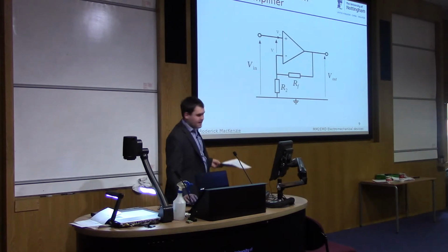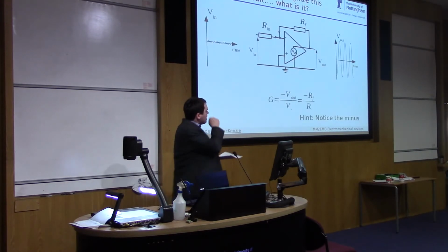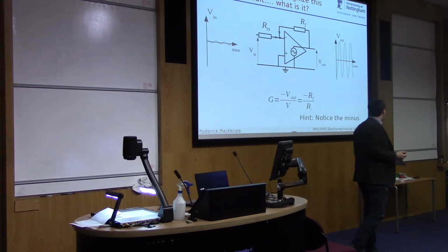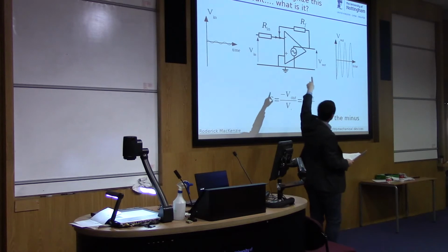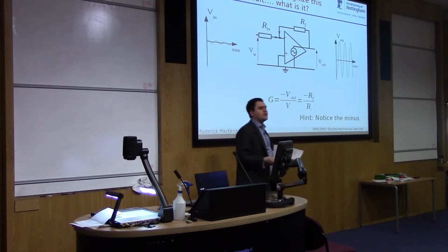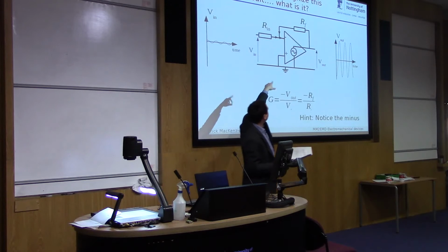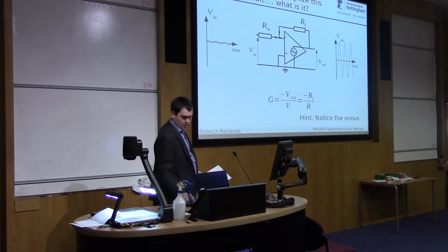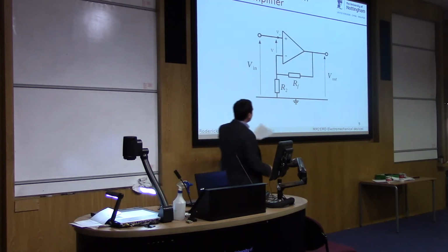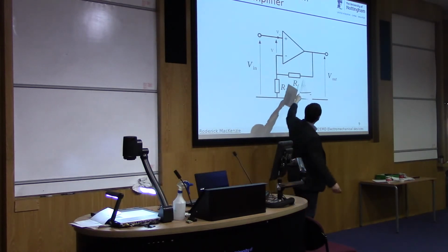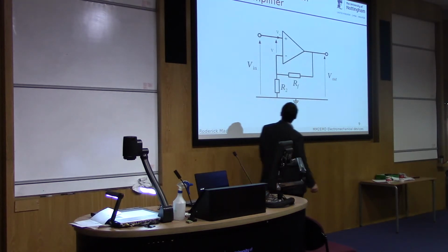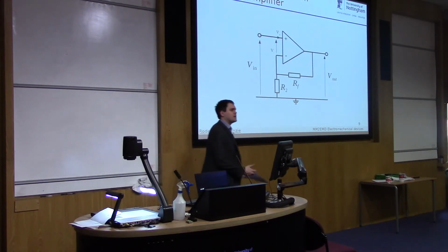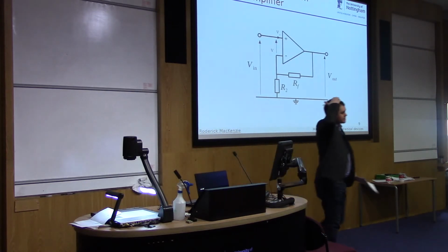And if you then look at the circuit, I know Arthur's been teaching about potential dividers. If you look at that top bit of the circuit, you can see it's a bit like a potential divider, and the centre of the potential divider is going into the negative pin. Well, you see the same type of thing on the non-inverting op-amp. You've again got this potential divider, and it's feeding back some signal. I'm going to show you how to analyse this circuit. It really is incredibly easy. It's much easier than any of the other ones we've analysed.